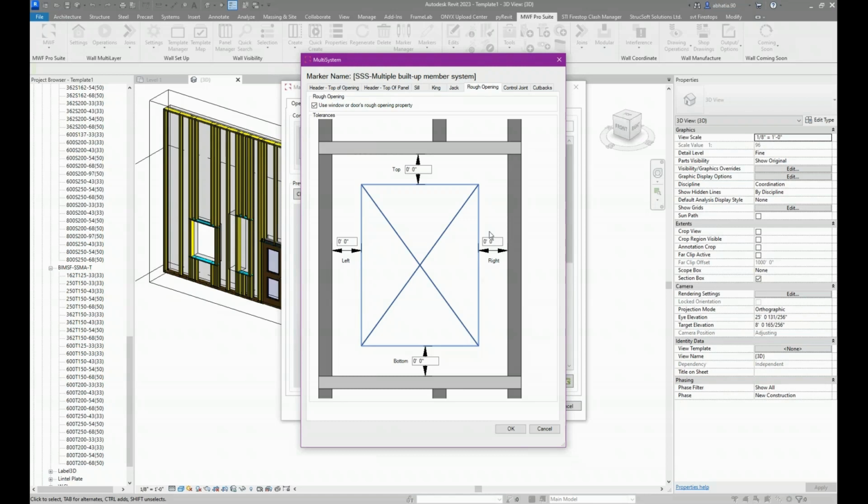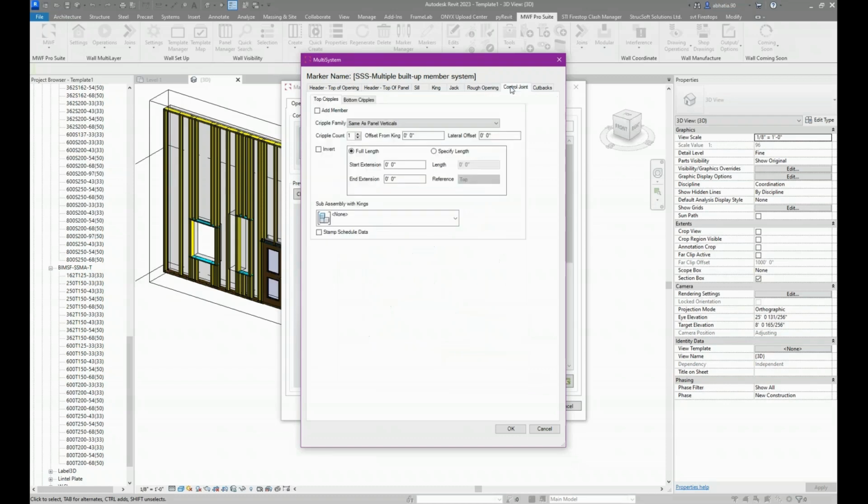So the more I constrain it with, like, oh, from the top of the opening, it always has to be 6 inches. If it's a default for the project, great. But you never know how the openings are built if you're using the architect's openings. If you're bringing your own in, totally fine. But just be mindful when you use this, it's going to happen at every opening, right? So that's basically what that is.